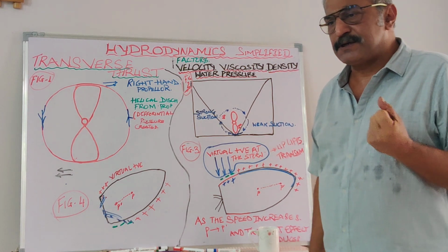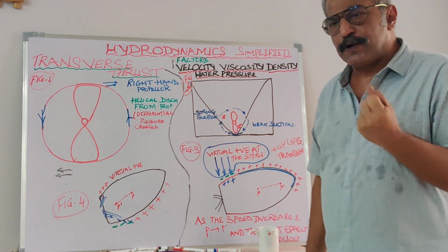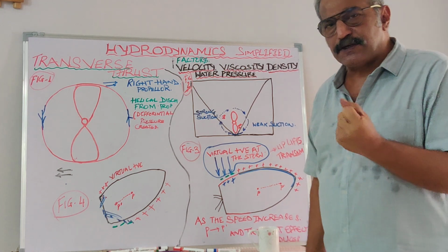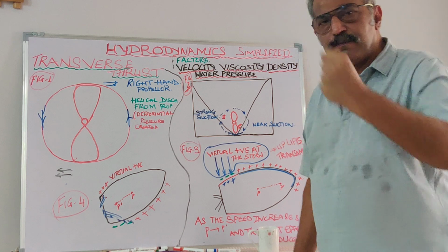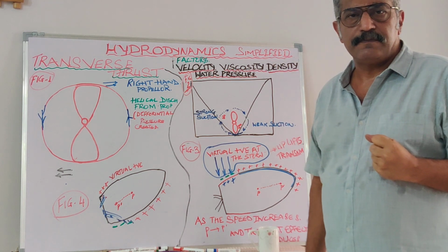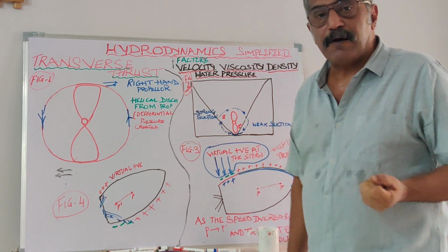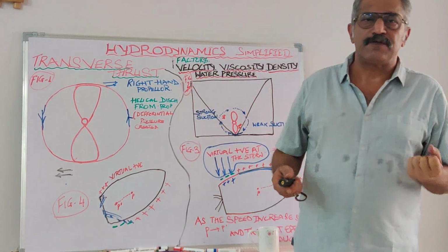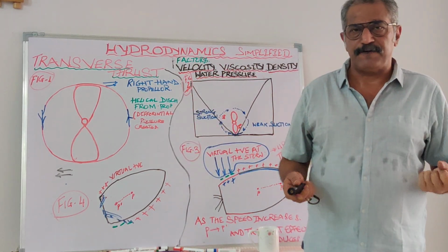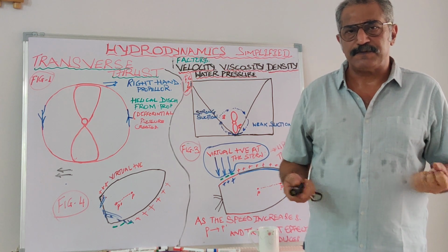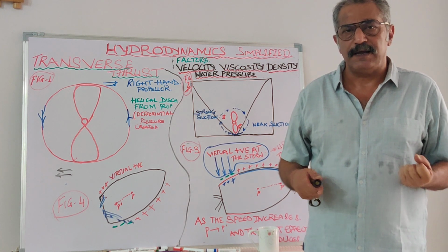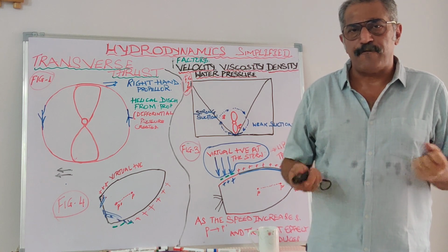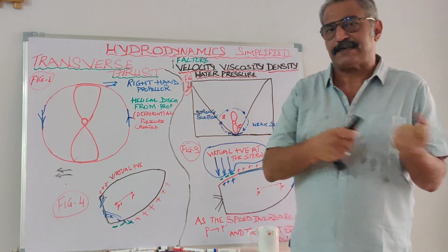Now, stern thrust: the output, with experience, is approximately 50% of the ahead thrust. In other words, the stern power, which many times the pilots also ask the captain, what is your stern thrust power? Some ships have 50. I've been on a few ships which have about 60 plus. But on average, we can take approximately 50% of the ahead power as the stern power.